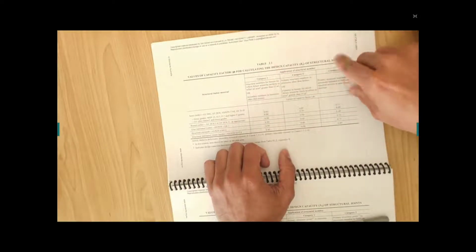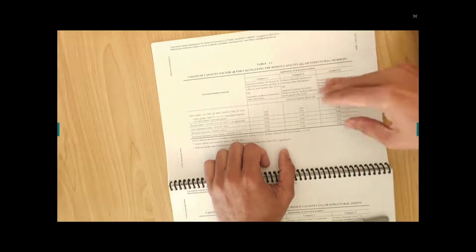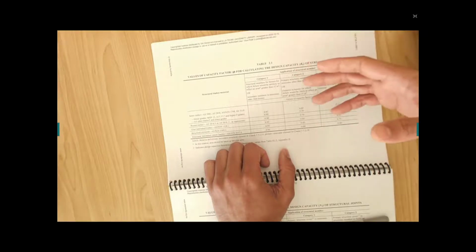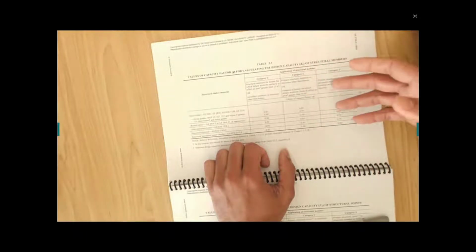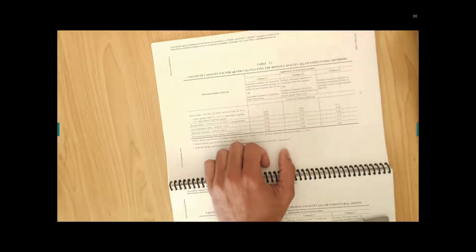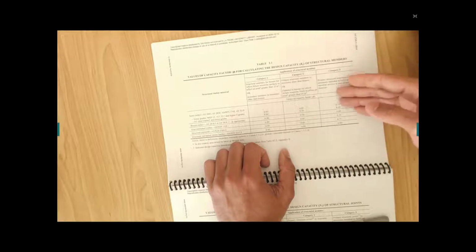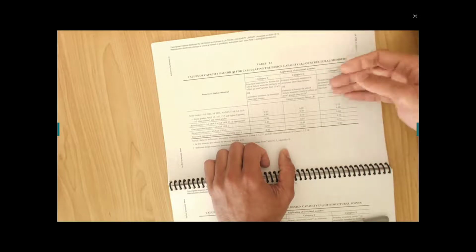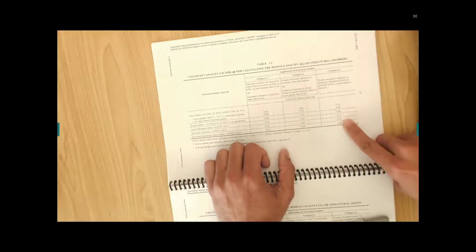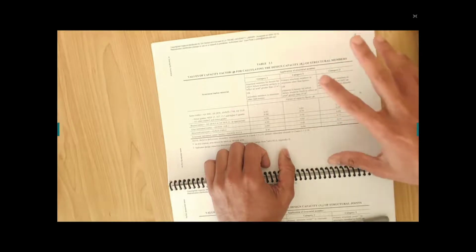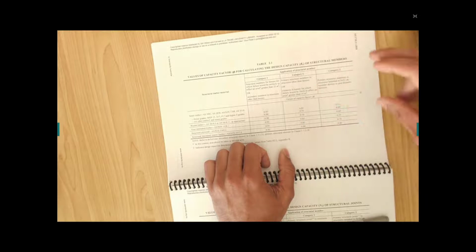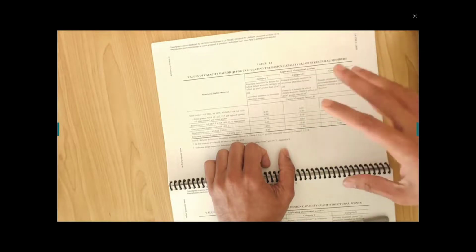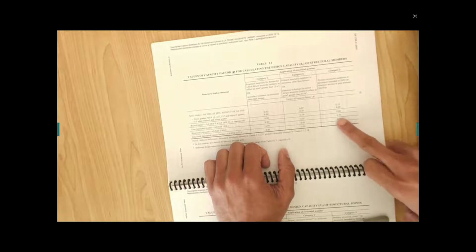And category number 3, if your timber beam is sitting in the hospital, the fire station, the police station, where the services are needed when a disaster happens, like for example the recent earthquake, if the timber beams fail in the fire station or SES emergency services, then they can't help other people, right? In that case, there is a severe penalty, meaning that your reduction factor goes up to 40%, as you can see. So this is the category for primary structures, where your beam is a primary member plus post-disaster functions. Hospitals, police stations, fire stations, power plants, all those things are sitting in this category.